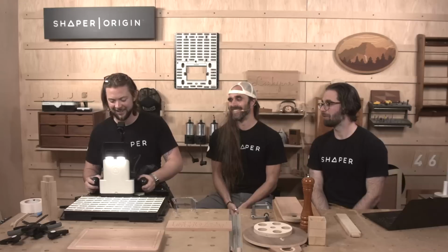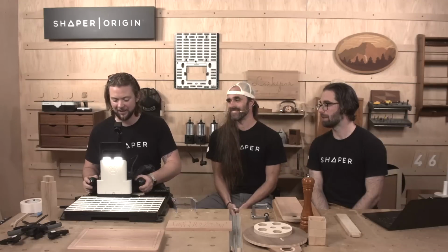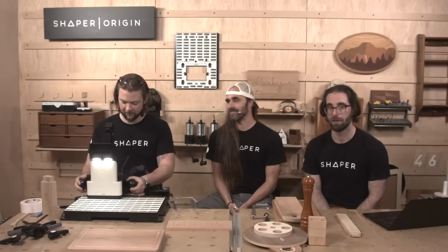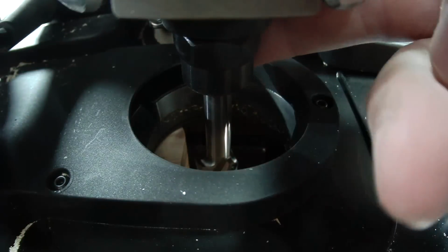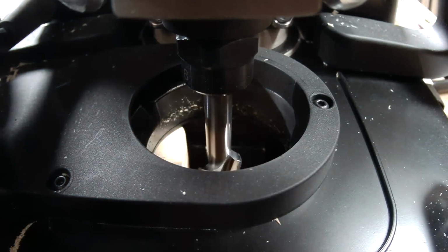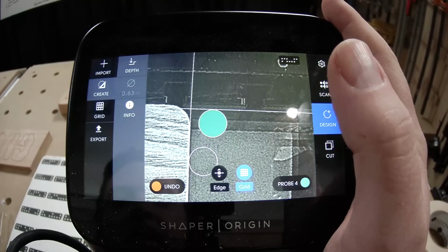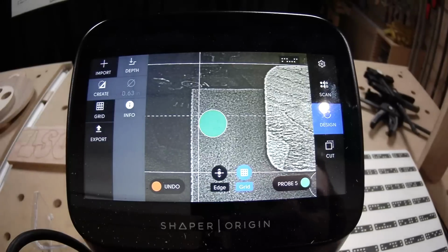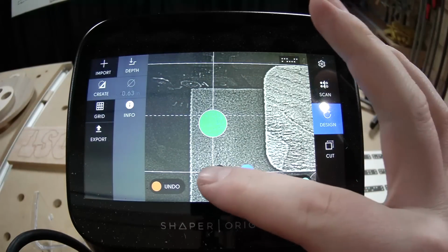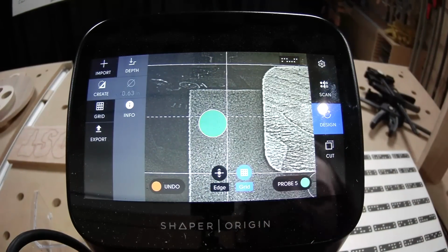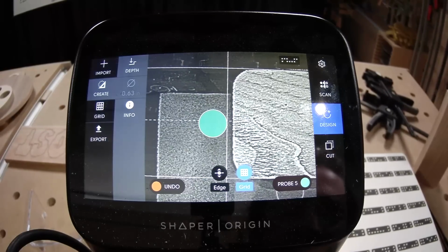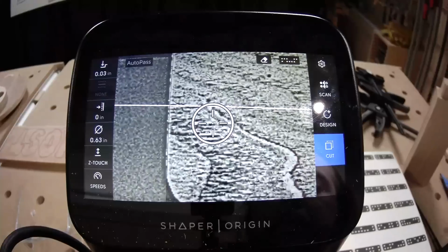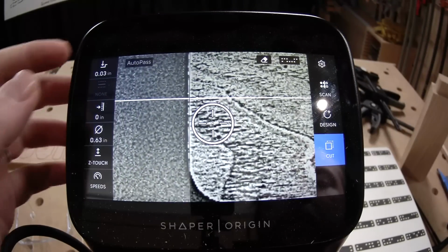All right, so Jake's being really careful here. He is probing with that 16mm bit, but he is being careful to make sure that he's referencing off of one of the edges of that bit, because you don't want to hit a low point when you're trying to probe. Yeah, this is a little off-label here. We recommend that if something's critical, you probe with the engraving bit for best accuracy. But you can do this as we say, not as we do. But for the sake of speed. The nice thing about this 16mm bit is that those gaps are so wide you can really feel when you're in between the edges.